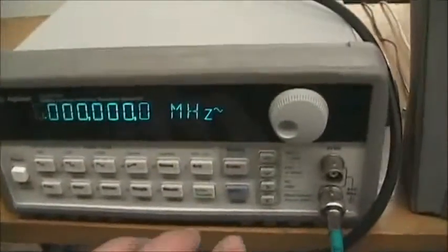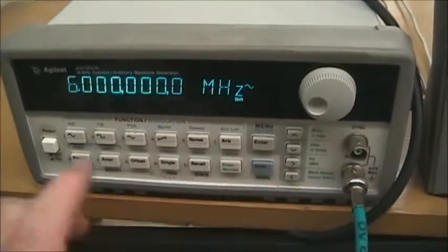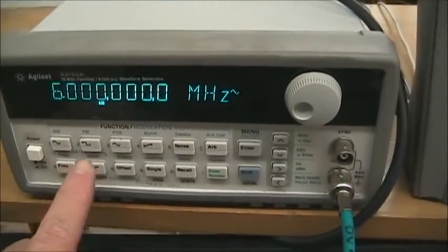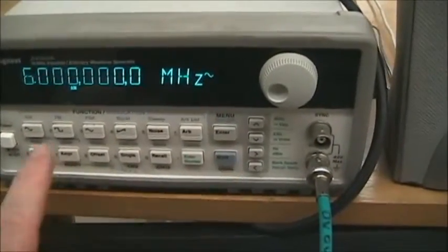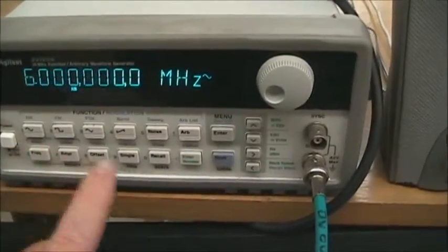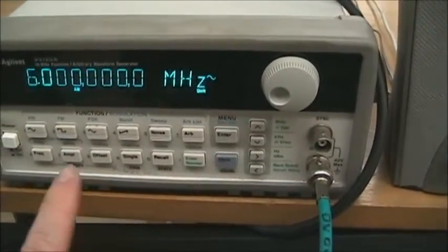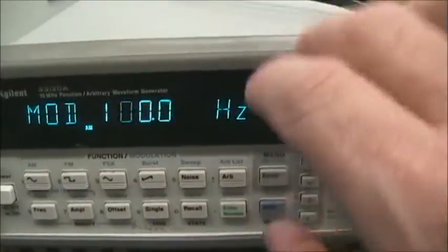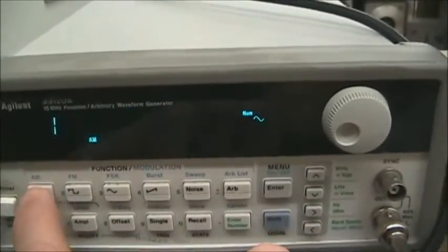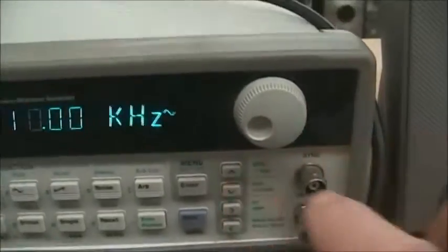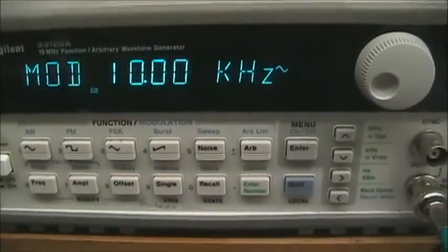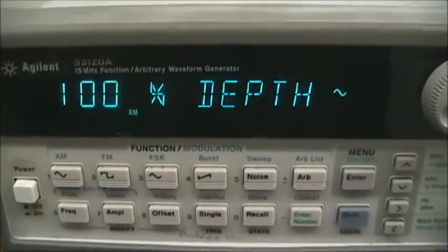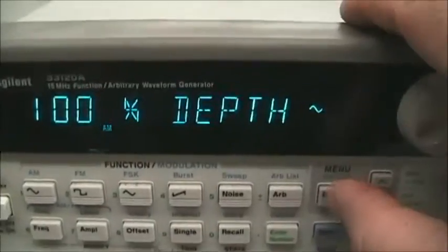So I will turn on the AM signal by using Shift and AM. You see an AM indicator. Under that case, the frequency of modulation is changed by shift frequency, the level by shift level. So we will change the frequency of modulation, and it is set at 100 Hertz. We'd like to use something like 10 kilohertz, so we'll enter that number, 10, and then kilohertz. So now we have 10 kilohertz modulation. If we want to check the level, it's 100%. MA is 1 or 100%, which is okay with us. So we're good to go.